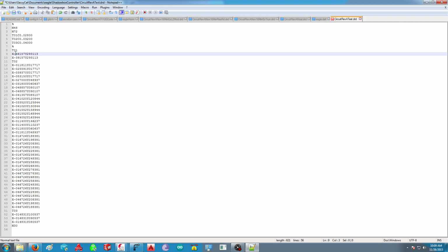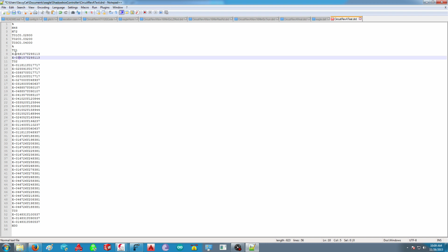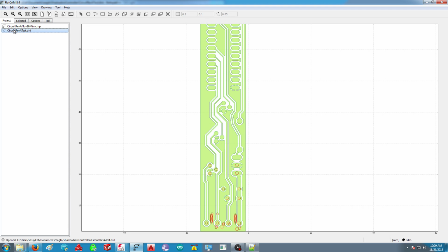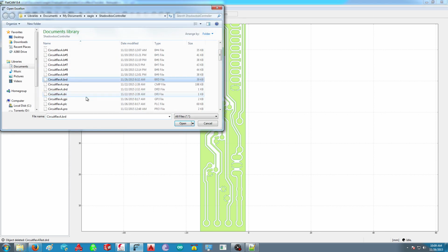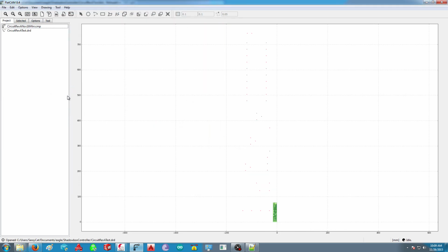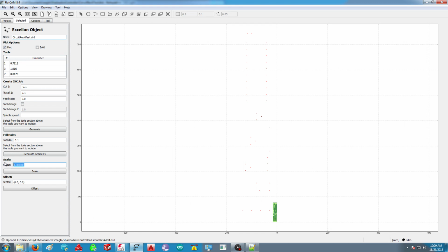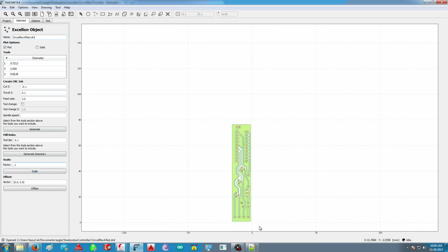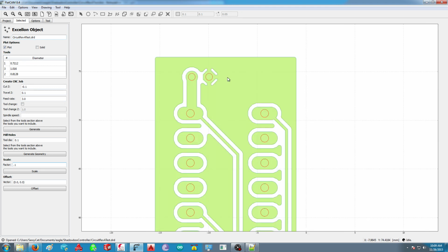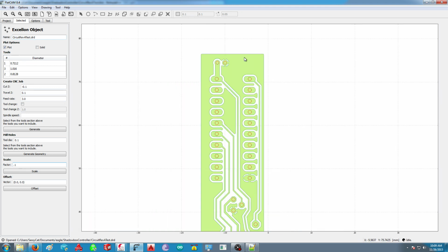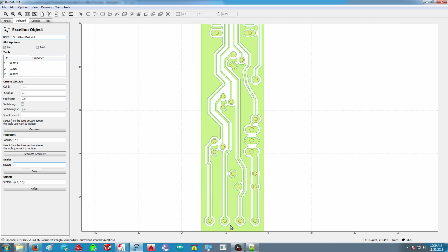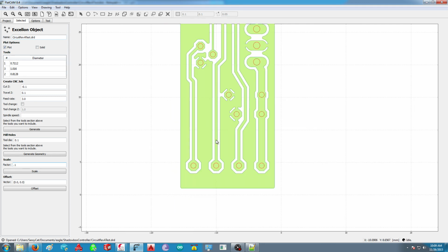There. Oh, up here too. Okay, so now all the XY coordinates have 6 digits in them. So if I now save this, go back, delete that, and open it up, I can scale that file down, and look. Everything lines up perfectly, and we just added zeros. We didn't actually reduce the resolution at all. So you don't need to reduce the resolution. You just need to give FlatCAM the heads up that 10 is 10 and not 1.